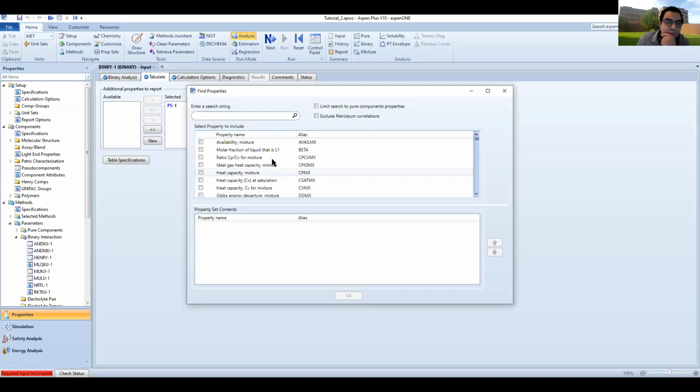So here you also have the option of selecting another parameter to plot for your system. So for example, because I have an XY system, maybe I want Aspen to also at the same time calculate the heat capacity of this mixture, calculate the enthalpy of this mixture. So you can always use this utility to tabulate it at the same time. I'm gonna get rid of this guy.